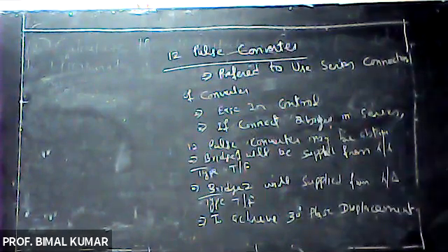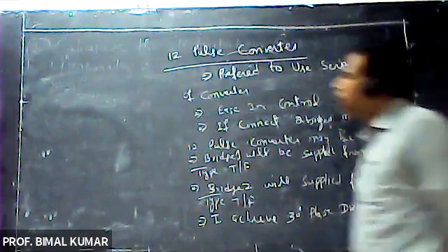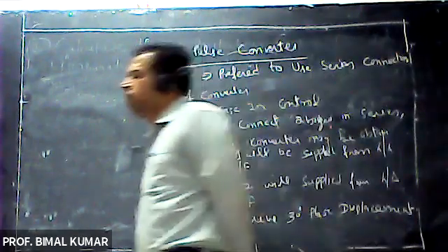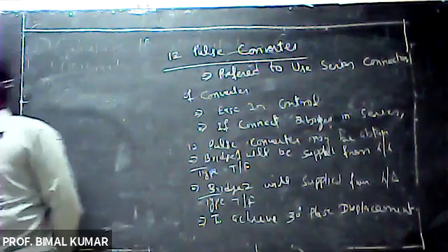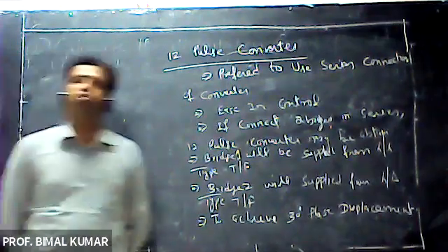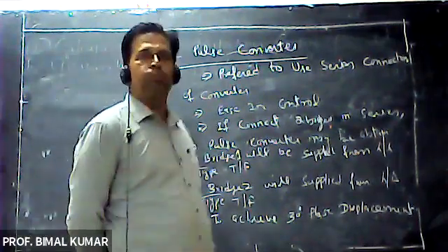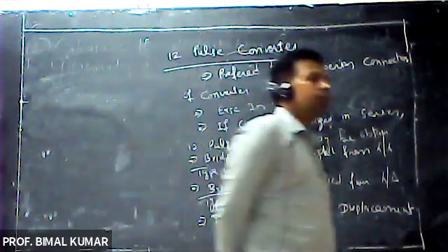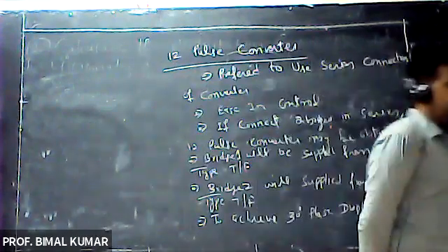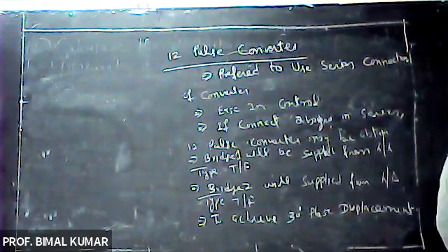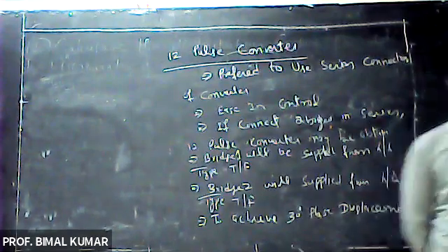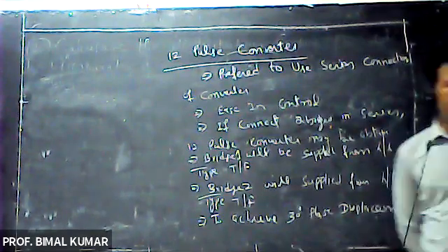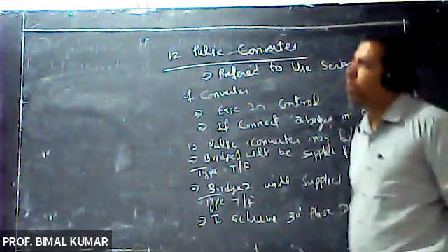Why? Because if we are using 12 pulse converter, then there is no requirement for filtering of the output of the converter, right? However, increase in pulse number beyond 12 is not practical.